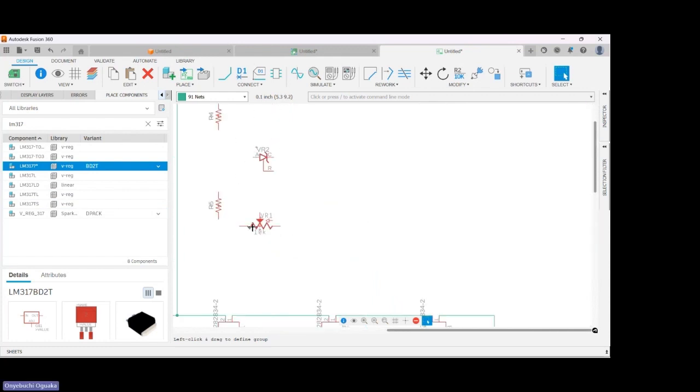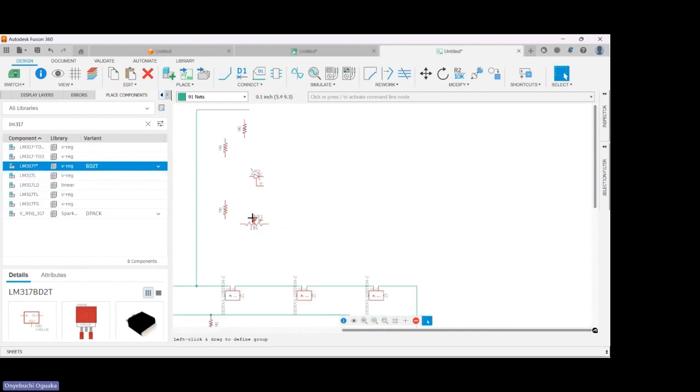So for here, you discover that this guy has no 3D model. So when we will be pushing our PCB to the 3D, you are going to realize that you won't be seeing this. All right, so that's the reason why you have to give the name, so that the manufacturer will know what you need in that empty spot. The name is going to be shown there, so that when they will be fixing everything, they will also get the required components and then fix it up. So that's just it. We'll be making our connections now.